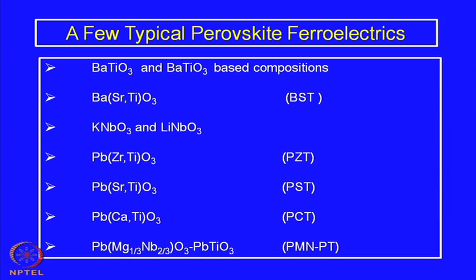compared to barium titanate, the susceptibility peak or the dielectric peak is a little different. It is a little broad peak, and it also depends on the frequency. So, it is a frequency dependent peak. The mechanisms are slightly different. Instead of a single relaxation time, there is a spectrum of relaxation times, and as a result you have a much broader peak in this group of compounds.